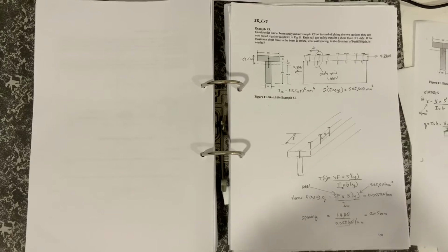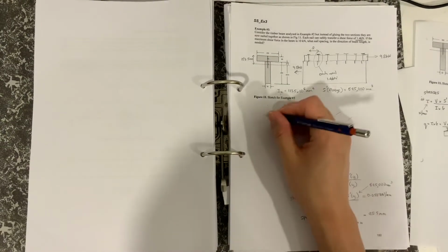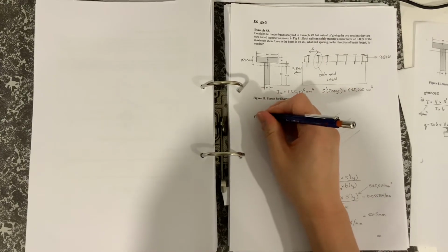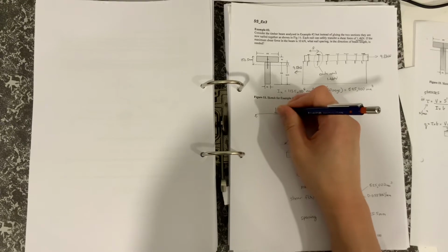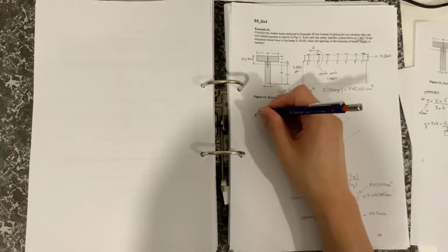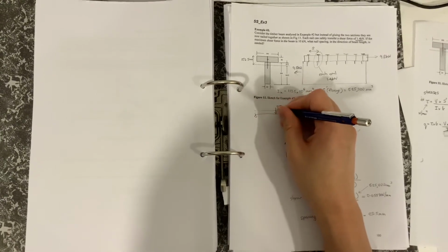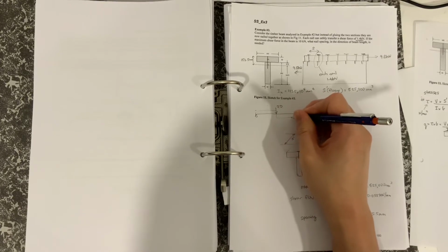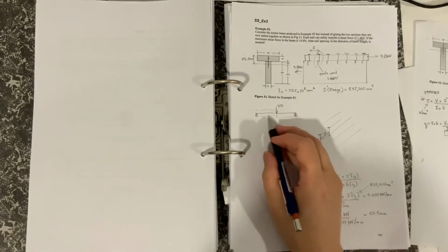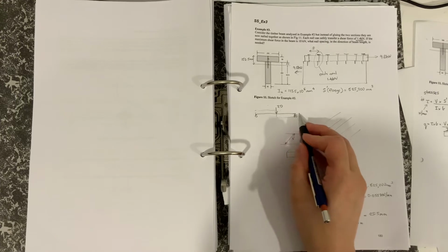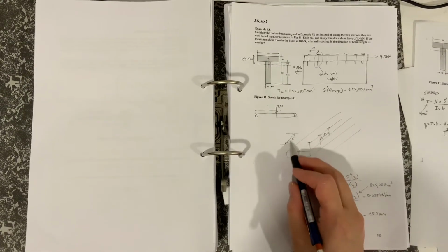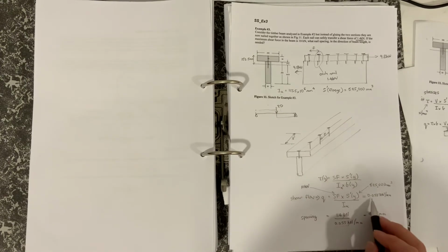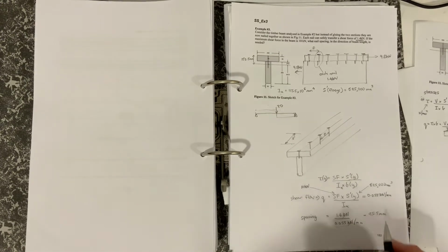So if, for example, that T-section had been a simply supported beam, like there, with 20 coming down here, we'd have the shear force diagram looking something like that, and within the length you would expect a nail spacing of 25.5 millimeters.